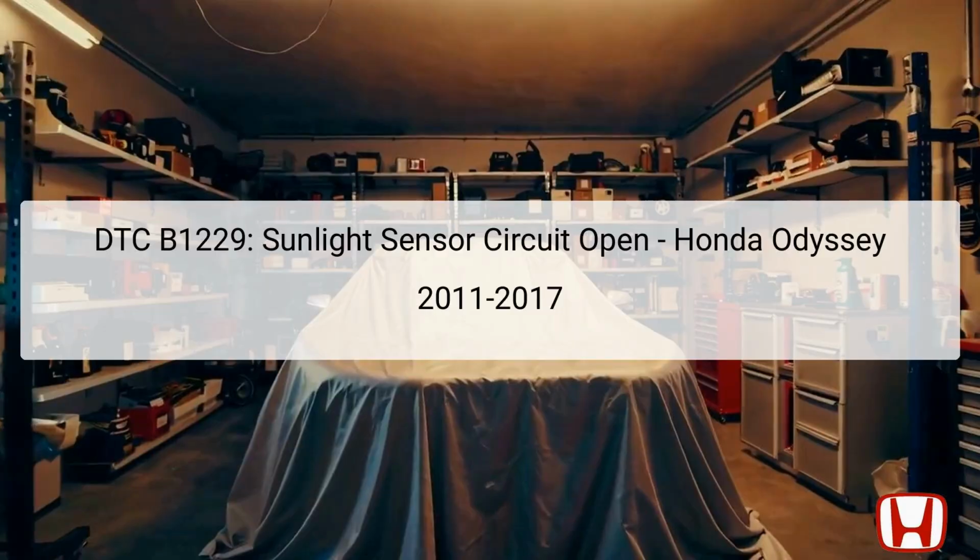This presentation addresses DTC B1229, which is flagged by the DTC indicator E and Auto in the 2011 to 2017 Honda Odyssey. The error signifies an open in the sunlight sensor circuit, which is crucial for regulating climate control based on sunlight exposure. The sunlight sensor, located on the vehicle's dashboard, detects the intensity of sunlight entering the vehicle and sends signals to the climate control unit to adjust temperature settings accordingly.